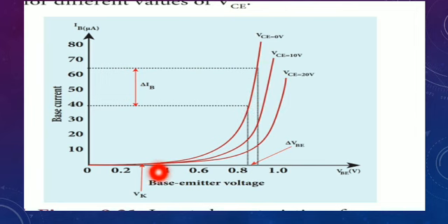And for collector emitter voltage of 10, the current will increase. The input characteristics are taken as the variation of base emitter voltage to the changes in base current at constant collector emitter voltage. Substituting that variation in the formula, we will get the input impedance.